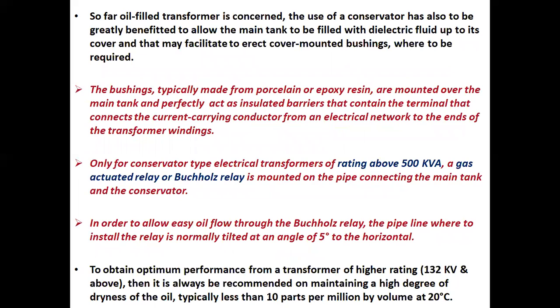So far as oil filled transformers are concerned, the use of a conservator also allows the main tank to be filled with dielectric fluid up to its cover, and that facilitates cover mounted bushings where required.